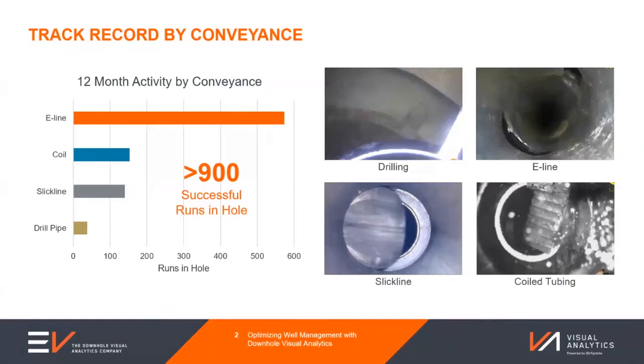Originally in the Haynesville, we were running memory PL strings with a memory camera on bottom. So that was back when we could only get like 5 hours of video on memory, but now you can run a tandem OPTIS Infinity and you could get up to 16 hours of video just on memory alone. So yeah, E-line would definitely be preferable, but you can get away with it with slickline, and you just have different challenges like you spoke on, be it a vertical well or horizontal.